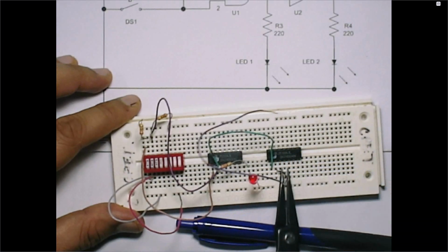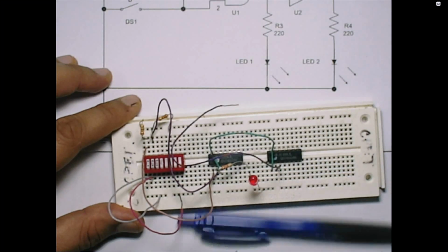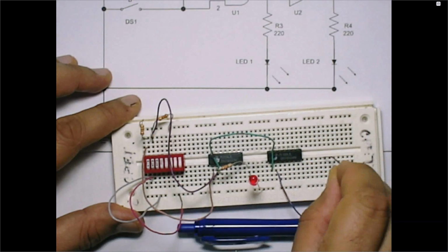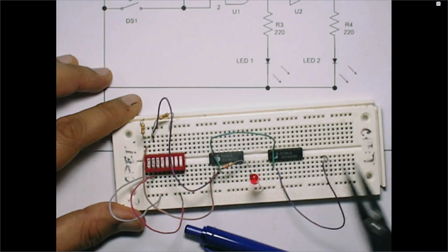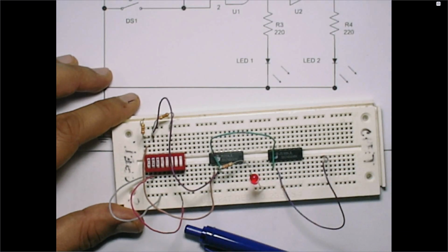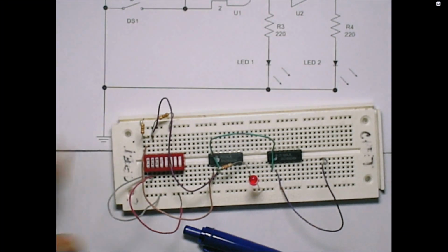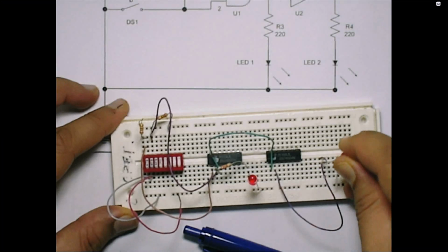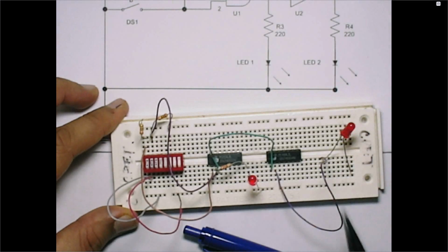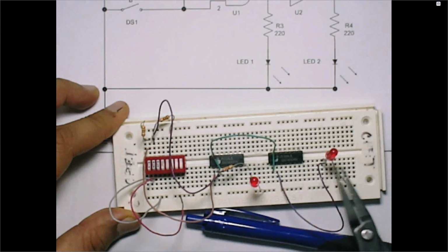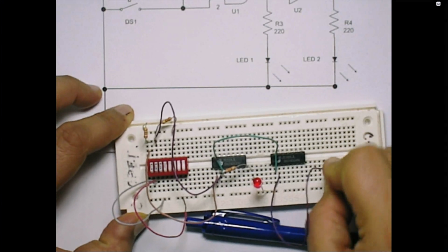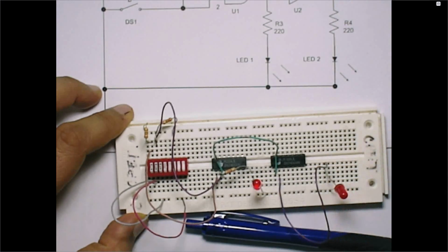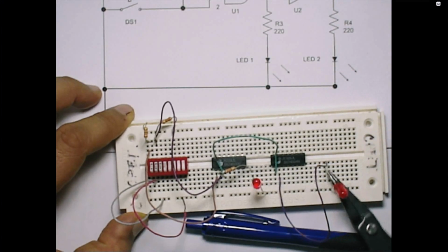I'm using my needle nose plier and a free column. Anytime you need an LED, use any free column which is not used before. I'm pushing it here, and then I'll be using an LED again, just like how I did before. Longer leg here. I'm connecting my longer leg here, and this is my shorter leg going to the ground. So this is my shorter leg, and this is my longer leg, because the shorter leg always goes to the ground.